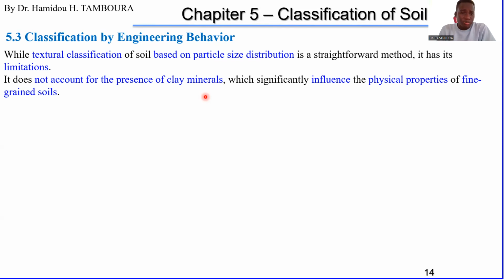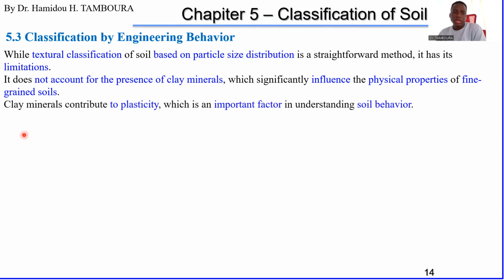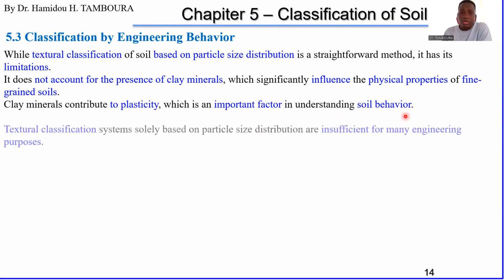Okay, so the classification doesn't take into account the presence of clay mineral, which is significantly important for the physical properties of fine-grained soil. And clay mineral also contributes to the plasticity, which is another important factor in understanding soil behavior.